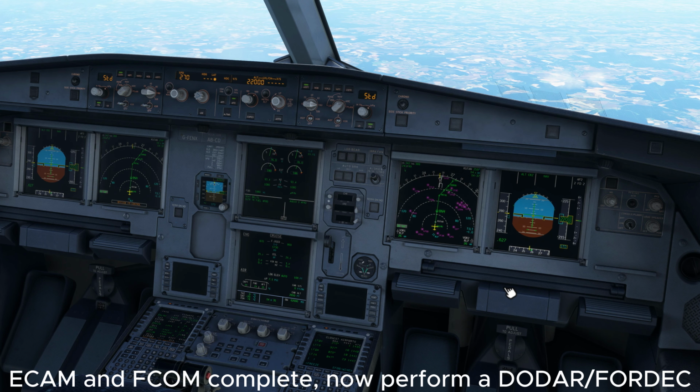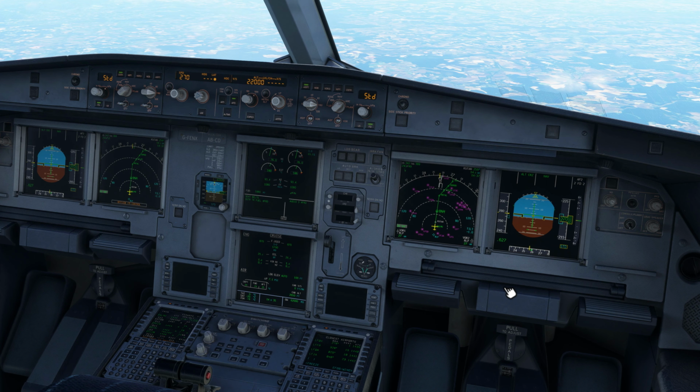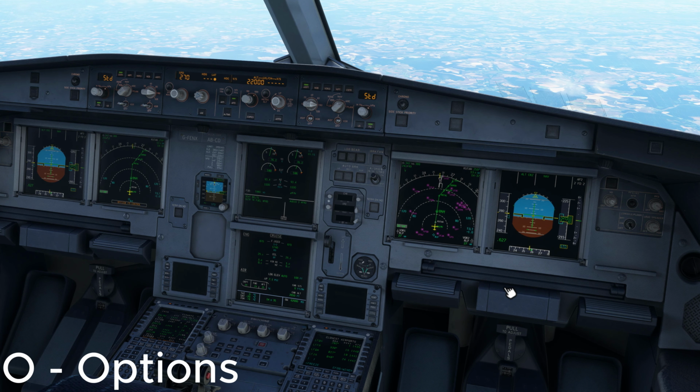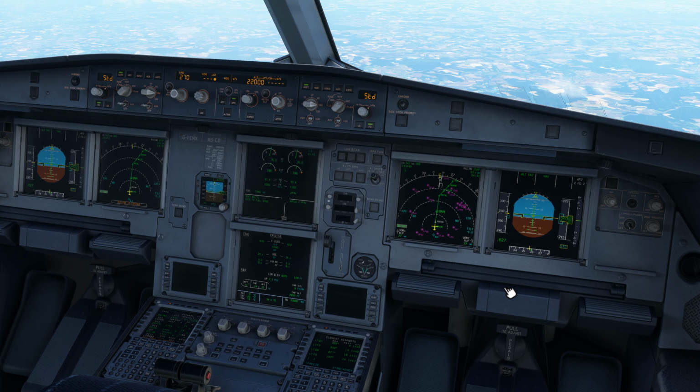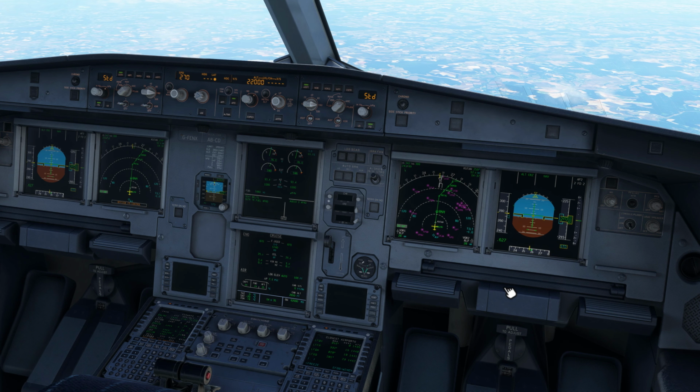D. We diagnosed the issue of a DC essential bus fault, and have discussed the associated failures. O. Options are continue, divert or return. We have Lyon and Geneva behind us. Paris is also about 100 miles to the northwest of us.